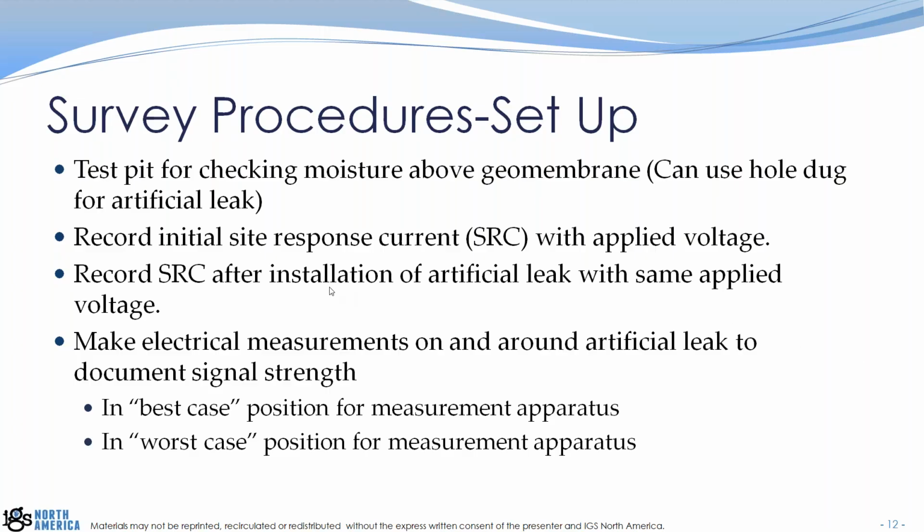We're also recording the site response current all the time with a slide voltage. We do it at the beginning. We do it when our artificial leak's plugged in. We do it throughout the day. We do it at the end. Why do we do that? We want to know how much the survey area is changing throughout the day. Is the cover material getting dry? Did the current go down when we dug up our leak? How much? It's also just a simple check to make sure that the survey was proceeding throughout the day. If you look and all of a sudden your output current is 0, your generator might have died on you. So it's creating that constant check to make sure everything is still working.